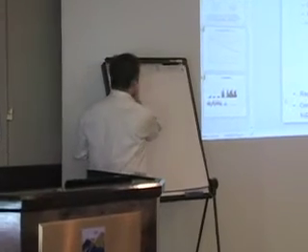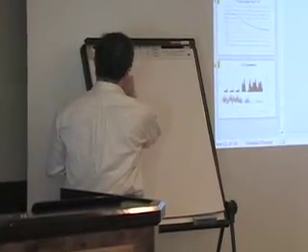Saying that Homer is saying, look, we need 200 kW of reserve capacity, even though we've got a primary and secondary load, or is it only looking at that primary load? Okay, so let's just work it out. Our operating capacity, so let's say the diesels are off, just for simplicity. So our operating capacity in that hour would be 200 kW, right?